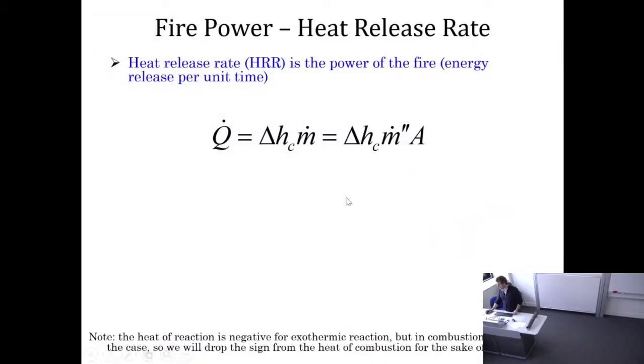But when you look into the heat release rate, which we're going to call Q dot, okay, that's the power of the fire. You know this. You can extract the heat of combustion, or the effective heat of combustion, of your polymer, and you know how to do that based on the chemistry and the stoichiometry of the reaction. You can develop the heat of combustion, which can be approximated as a constant or a property, a combustion property of the polymer or the material.